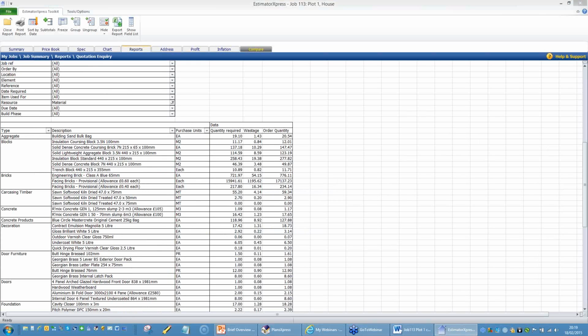The other thing to bear in mind is that the software automatically allows for what we broadly call wastage. Now, wastage in some sense is a bit of a catch-all because it takes account of a bit of rounding, because sometimes you can't buy 15,800 bricks, but the wastage factor is making allowance for that. We know that stuff gets nicked. Why would you allow a wastage factor on, say, a window? You can't really waste a bit of a window, but again, we know on average stuff gets nicked, it gets damaged, and the wastage factor attempts to deal with those sorts of things.